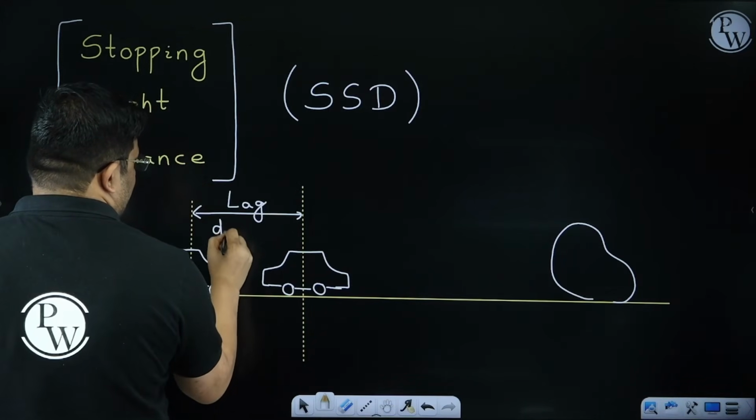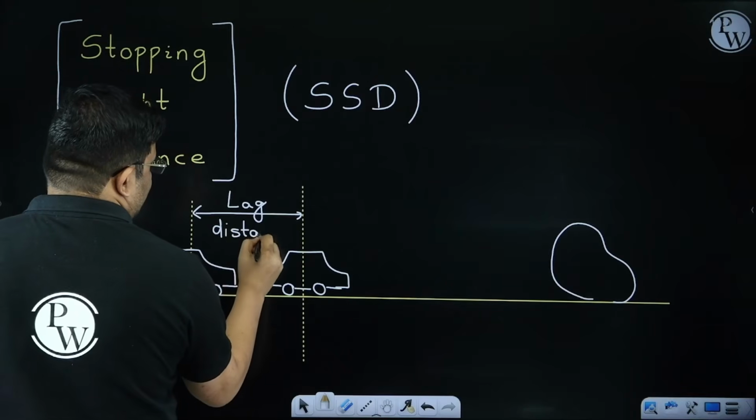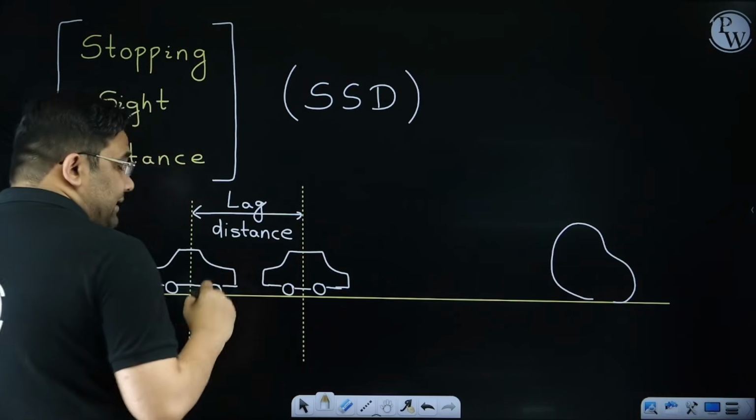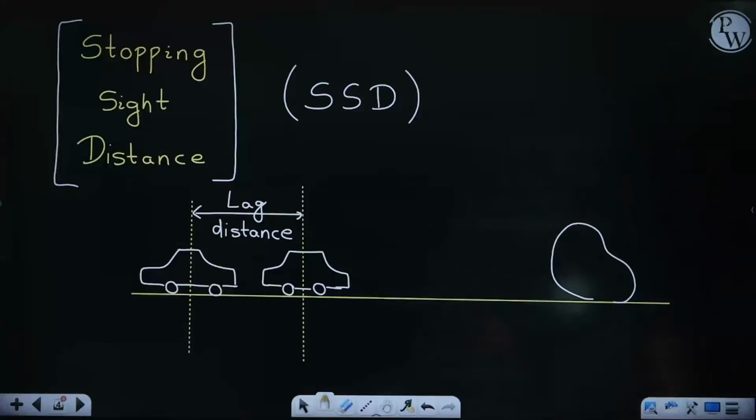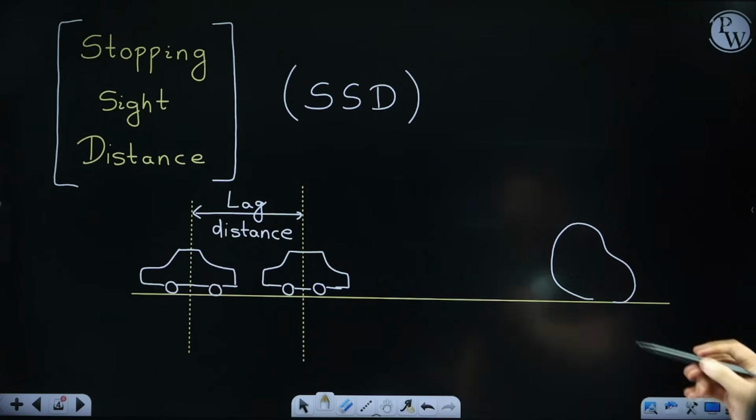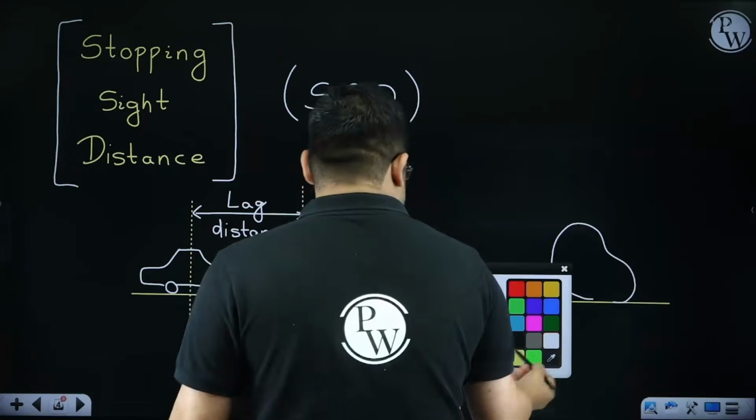So what is lag distance? I can say it is the distance traveled during the reaction time of the driver. This is known as your lag distance. And how to calculate this?